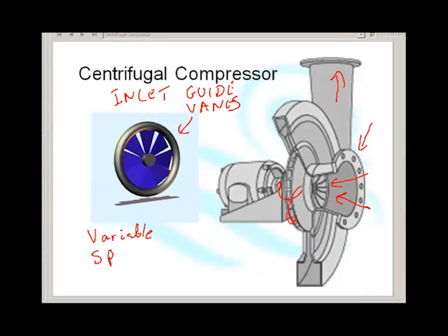Variable speed drive, or variable frequency drive, or in Europe they're called inverters. So nowadays we can VSD. So increasingly nowadays compressors are coming fitted with VSDs, and we just wind the thing down instead. That works really quite well.